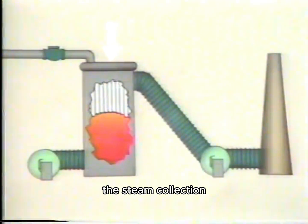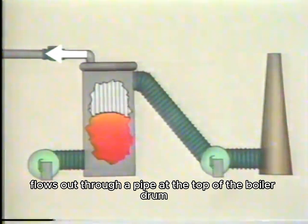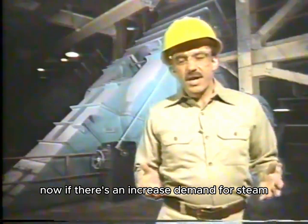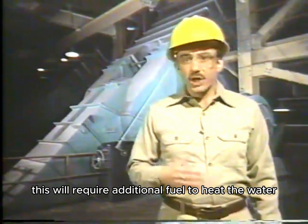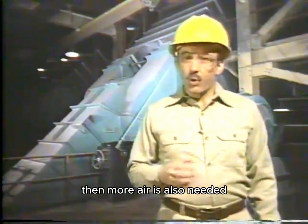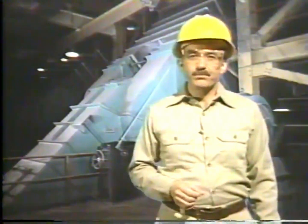The steam collects in a boiler drum, similar to the kind we looked at earlier, and flows out through a pipe at the top of the boiler drum. Now, if there's an increased demand for steam, then there will be an increased demand for water to be converted to steam. This will require additional fuel to heat the water. And if more fuel is needed, then more air is also needed to maintain proper fuel combustion.